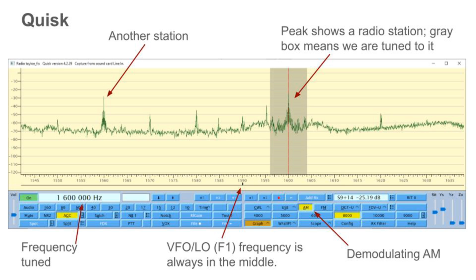The frequency of the square waves the Pico produces sets the center point of the display. Radio designers call this the local oscillator or VFO frequency. The display is showing the upper part of the AM medium wave band in the United States. The LO frequency is about 1589 kilohertz. Values up to about 15 or 20 megahertz work in the simple radio. Let's give it a try.